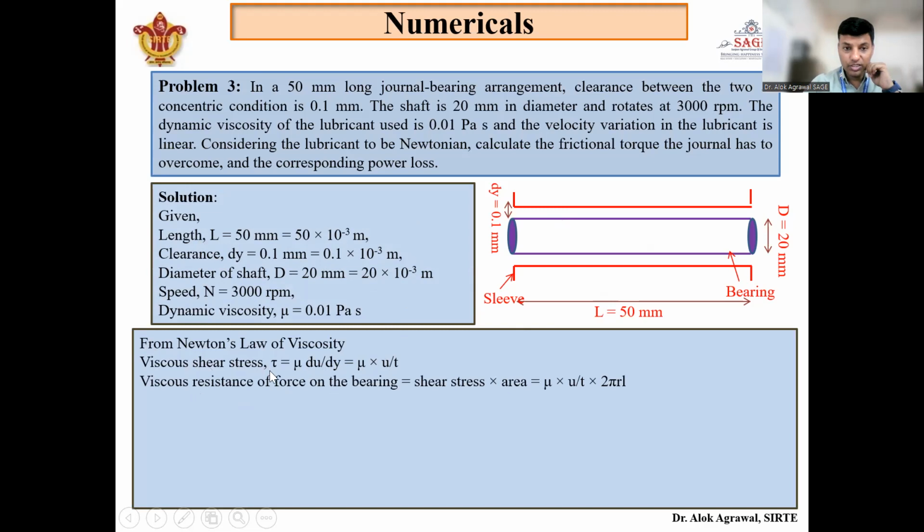Now viscous shear stress is converted into shear force by multiplying this by area. What will be the area here in this case? The curved surface area of the bearing, because oil is in contact with the curved surface area of the bearing.